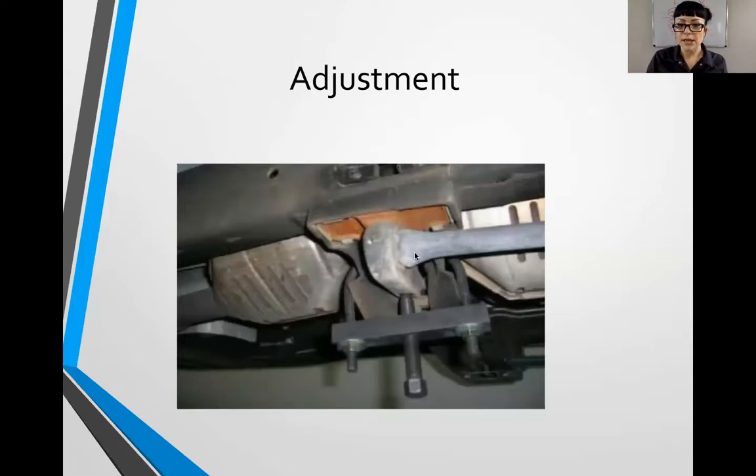If you look here, our torsion bar is fixed to this sort of lever piece. It's a key, essentially. So it fits in here kind of like a key, but I can actually twist the torsion bar in a fixed position by changing that lever point and tightening or loosening a bolt.